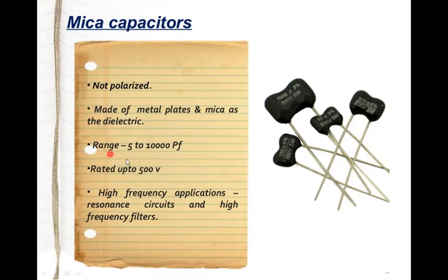Mica capacitors have a range of 5 to 10,000 picofarad, rated up to 500 volt, and the applications are high frequency applications like resonance circuits and high frequency filters.